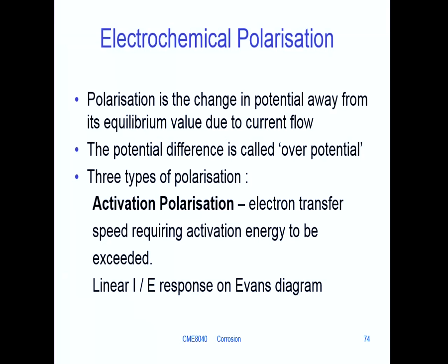So this type of polarization is not about the process being slow, it's just about it requiring you to exceed an activation energy. And you'll get the linear response that you get on an Evans diagram. We'll have a look at one in a minute on your handout. I'll come back to that.